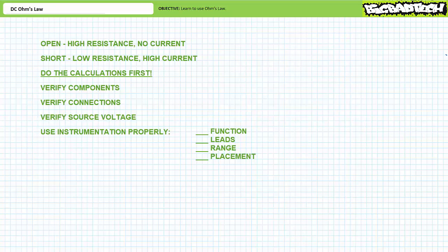every single time. Function. Choose the quantity you want to measure: voltage, current, or resistance. DMMs use different detection mechanisms to measure different quantities, and if your DMM is in the wrong mode, it won't work. Leads. Put your leads in the correct place. For voltmeter and ohm meter mode, the leads go in one place, and in ammeter mode, they go in a different place. Of note, customarily the red plug goes into a red hole, and the black plug goes into a black hole. You would be surprised how many people mess this up under stress.